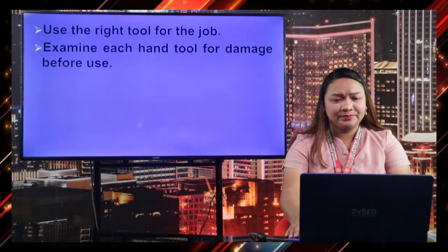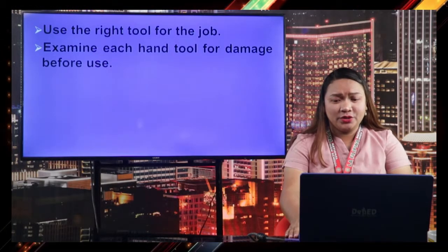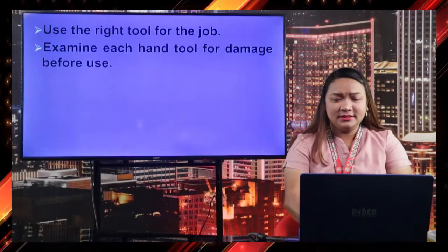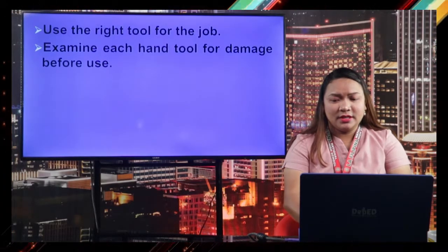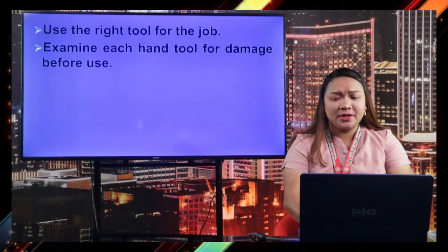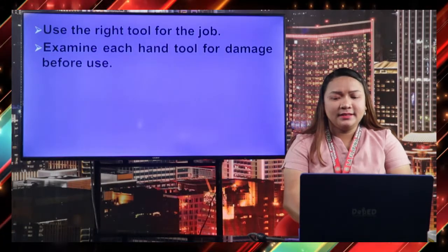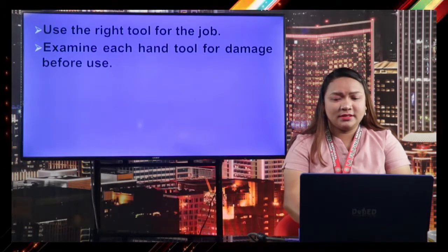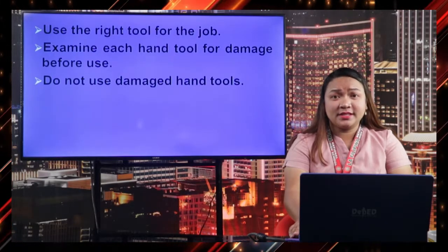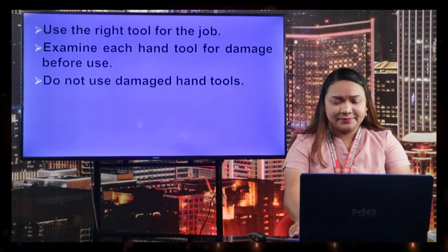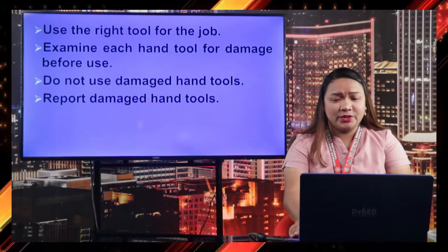Next, number 2, examine each hand tool for damage before use. So check the handle and body casing of the tools for cracks or damage. Check its physical appearance for dullness, sharpness, and dismantled parts. Next, do not use damaged hand tools. Next, report damaged hand tools.